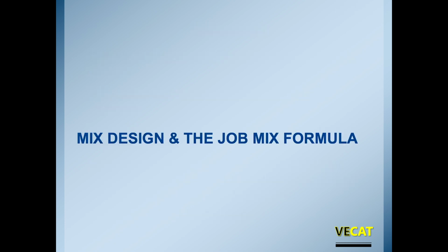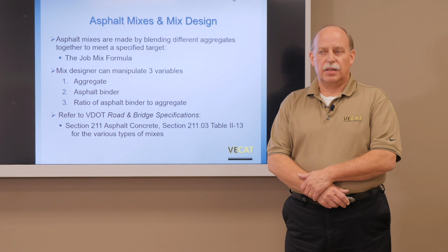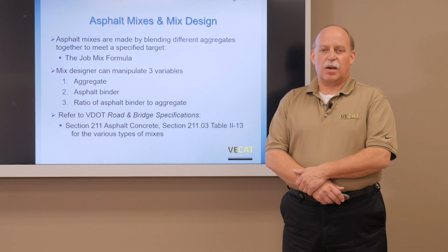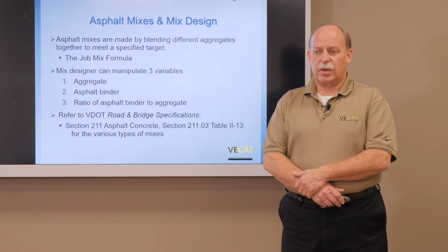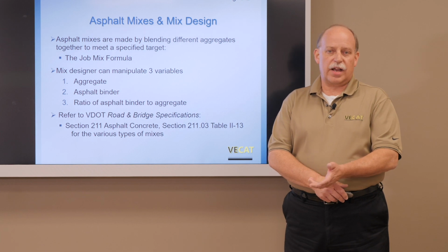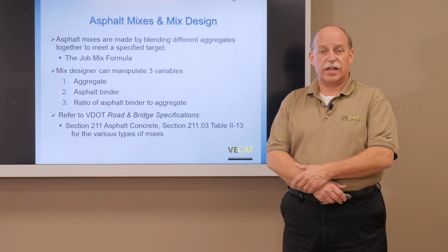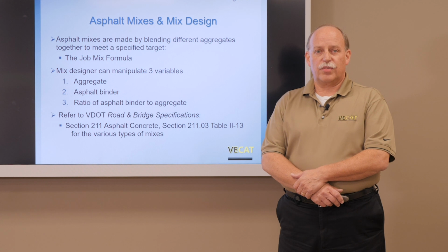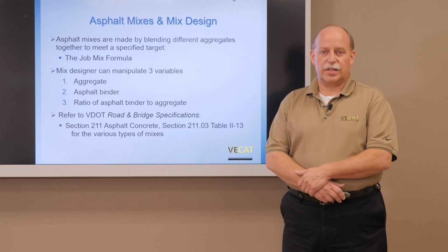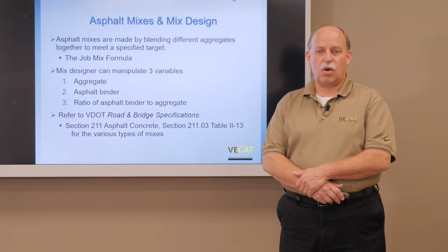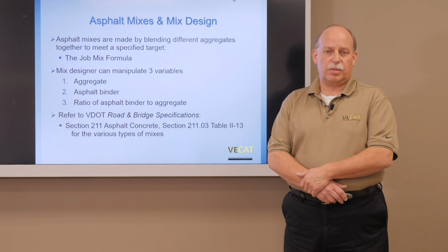Before I get into the actual blending of the aggregates, let's talk for a minute about mix design and specifically about the job mix formula. Asphalt mixes are a very complex mixture in reality. The basics tell you that they are a combination of aggregates and liquid asphalt, and that is a very true statement. However, you have to take all of those ingredients together to produce a mix that meets all the requirements to be placed on a typical roadway surface.